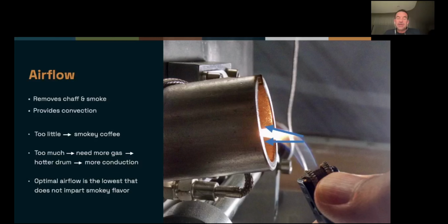And this is because when you increase the airflow, the burner will work harder in those machines to maintain a certain inlet temperature. So the bottom line is that we're only worried about minimizing the airflow to the lowest acceptable level in classic drum roasters. In other types of machines, there's a lot more freedom to use different airflow settings. Are we all caught up there?